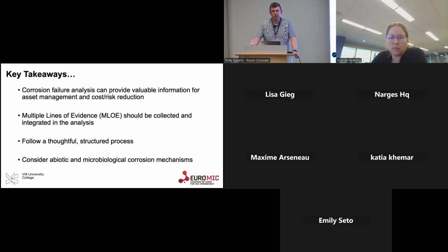Yep. They do that also with thermographic identification, because the sediment will be colder. There are all kinds of means that they use, and that's also what they feed into the risk-based inspection programs, where to look. But a dead leg is always a red flag. Let's go look there. Yep, good points.